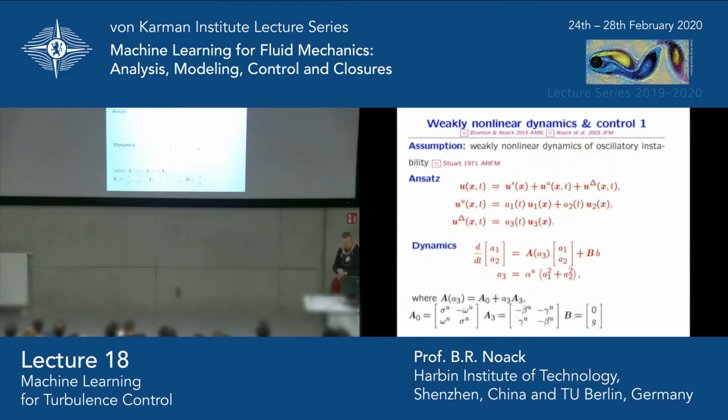We have also talked about non-linearity. So there is one non-linearity associated with a Reynolds stress. The average flow does not stay as a steady solution. You move away. We have seen it in my first talk. Now you decompose the velocity field in the steady solution, in the first harmonics, and in the mean field deformation. Again, first harmonics, mean field deformation. You get such a dynamical system, which we have discussed earlier. So there is an oscillation where the growth rate is determined by A3. A3 is the shift mode, it's a base flow variation, and this is proportional to the Reynolds stress.